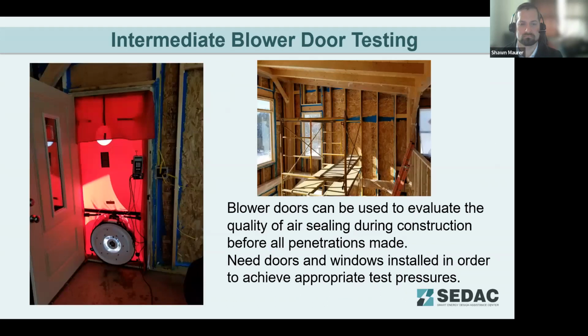So blower door testing does not have to be a once and done thing. One can use blower door tests throughout construction. The first, you could potentially do a test run as soon as your envelope is complete. Once you've got your framing up and your windows in, before you've made any other penetrations, as soon as your envelope is complete, you can perform a blower door test just to see how good was my envelope before I impaired it at all, and starting to understand, because I'm going to make penetrations, I'm going to make this worse. Understanding before you've made any penetrations, how close to that mark are you going to be?